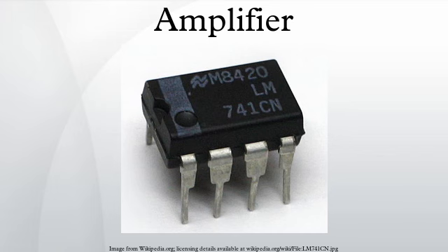For those who prefer low distortion figures, the use of tubes with Class A together with symmetrical circuits results in the cancellation of most of the even distortion harmonics, hence the removal of most of the distortion. Historically, valve amplifiers often used a Class A power amplifier simply because valves are large and expensive. Many Class A designs use only a single device. Transistors are much cheaper, and so more elaborate designs that give greater efficiency but use more parts are still cost-effective.